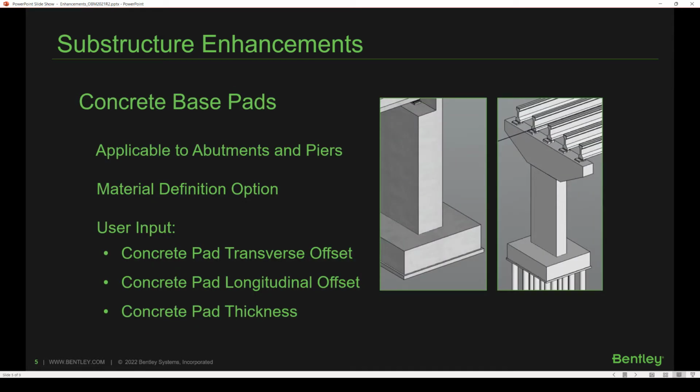The second enhancement that we will cover in this video is concrete base pads that can now be placed under abutment and pier footings. Concrete pads, also known as seal slabs, have the material definition option and require transverse and longitudinal offsets and thickness as user input.